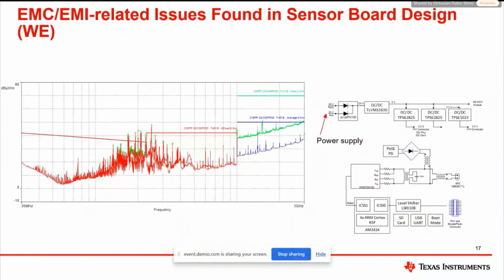Now, we talked about the evaluation board, the reference design. So let's look at TIDA 010261. This is the reference design, and we supported with checking the EMC performance. We did the tests in our labs. We also supported the engineer with the debugging process and optimization process. The EMC performance was tested against CISPR 32 Class B.